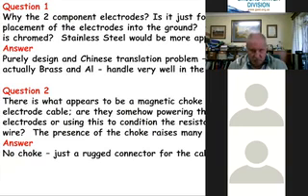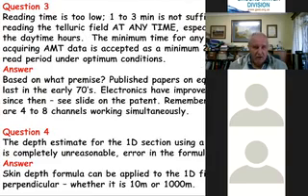And where are you looking for water? It's generally in an arid region, so therefore the surface is also relatively arid. On reading times, 1 to 3 minutes is not sufficient for reading the telluric field at any time. This was a purist's view, at a minimum of 20 minutes, with 1980 development electronics. This is now 2020, and electronics have improved quite a bit since then.